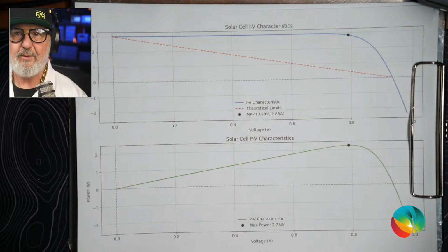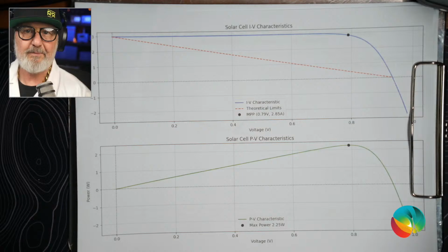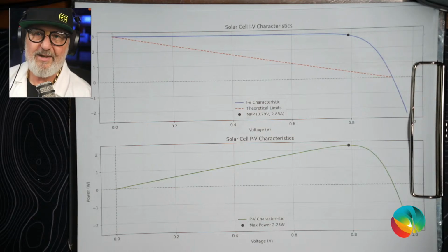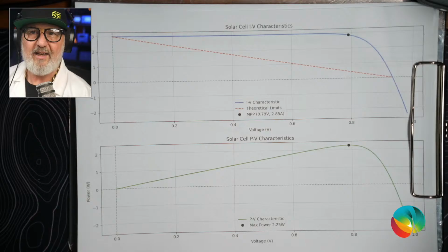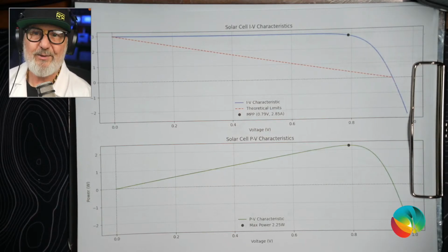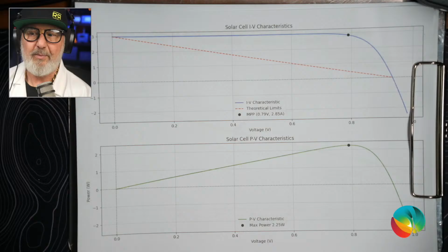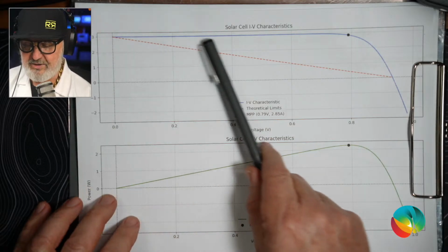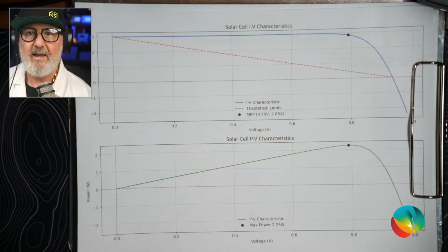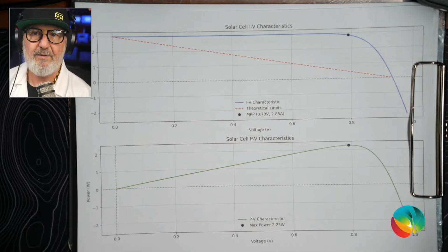So why are we going here? Well, the fact that a solar module is actually a kind of non-linear power source. What I mean by that? Well, it's definitely a linear current source. That means if you double the solar radiation, you double the output current. But when it comes to power, it's not linear. And the reason for that is the load line, which is this blue line here, is the operating line of a solar cell. In this case, it's just a single solar cell. The same would be for an array.